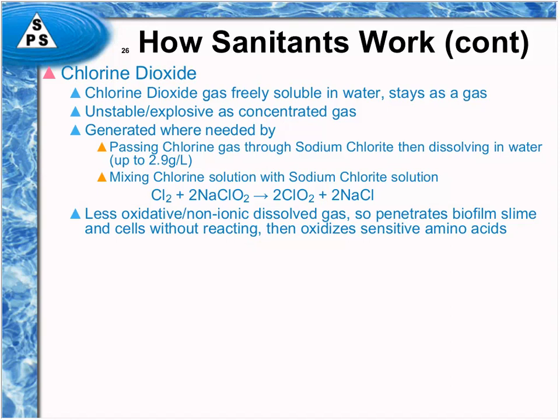It's less oxidative, and it's not ionic. Less oxidative than the other sanitants, but the combination of its lower oxidation potential and its non-ionic nature allows it to dissolve into and penetrate the slime of the biofilm without reacting with the organics in the slime. It doesn't have an oxidation potential high enough to chemically react with the polysaccharide molecules inside the slime.